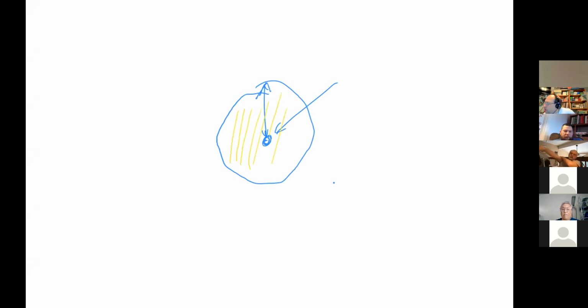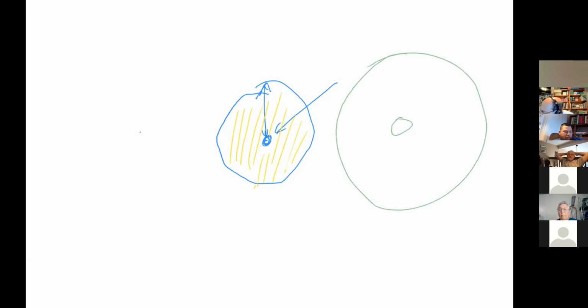Now, what makes a cable 50 ohms versus 75 ohms, if I were to draw it from the end, is the ratio of the diameter of the center conductor to how far apart they are. We can also have the material inside that changes the dielectric constant a little bit. So essentially we have a combination of things which we can scale up if we want to, or scale down.